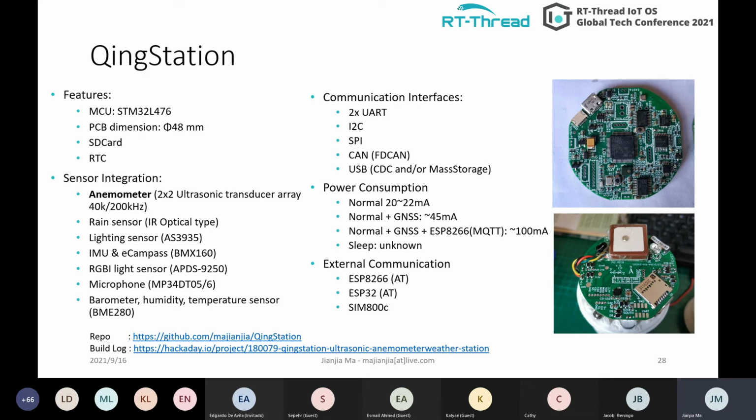There are also very good functions where I don't even need to write a single line of code. I can enable them, including USB CDC or USB mass storage class, CAN bus communications, UART communications, and all the drivers. Some other functions like the RTC can just be enabled if you tick the box.